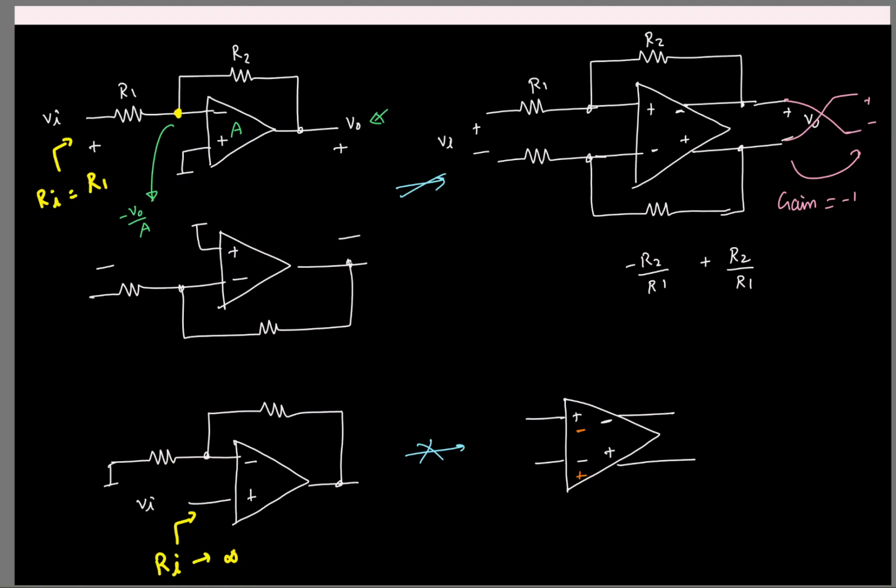So essentially, if A is large, this quantity is going to be really small, right? So the point I'm making is the actual swings that go into the op amp inputs are quite small. And remember, these inputs are straightly connected to the gates of some MOSFETs. So the swings at the gates of some transistors are going to be really small.